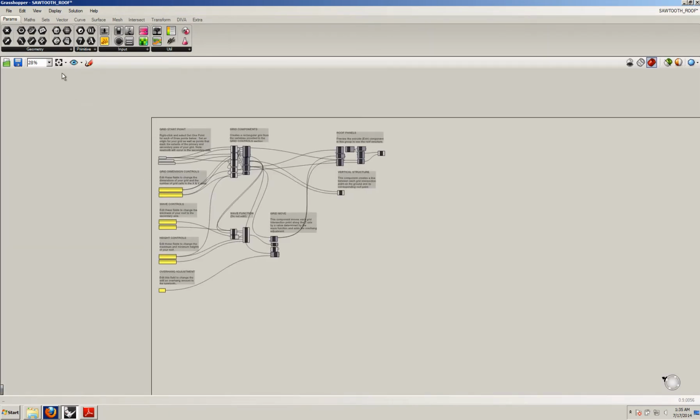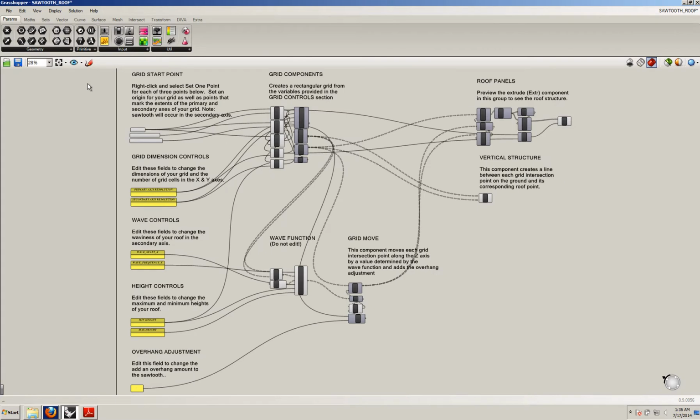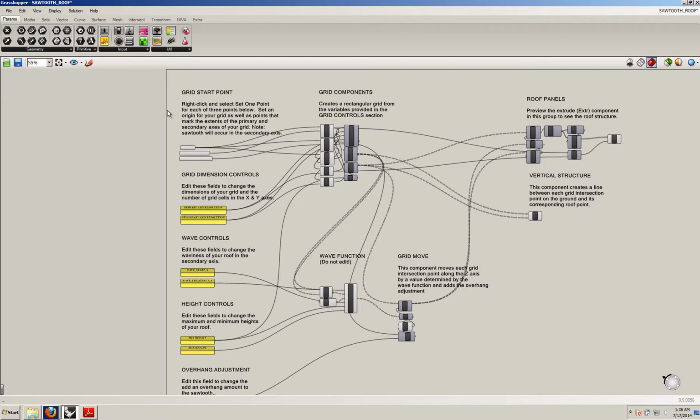Rhino file. So you can maximize the Grasshopper viewport by minimizing and maximizing the window, and then the four-corner icon here allows you to zoom to the entire document. So it'll zoom to the extents of the entire Grasshopper script. Typically we read scripts top left to bottom right, so top to bottom and then left to right.